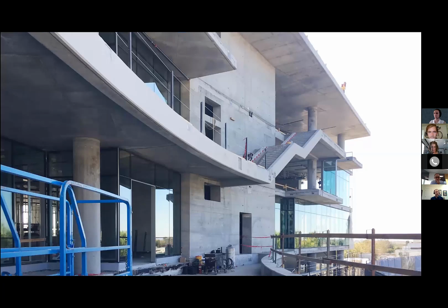When you strip that back, it is a concrete building. It has a lot of concrete within the building. As we looked at it, about half the concrete, give or take, is in the PT floor slabs, maybe 30%, give or take, is in the foundations, with the balance being in the core walls and the columns.